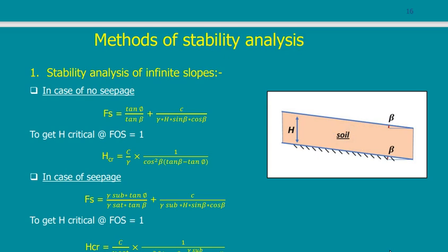Sometimes you might have seen videos of something called mud flow, where something like a mountain is moving down to the bottom. What is happening? You have a top soft soil, and this soft soil is very, very soft and does not have any shearing resistance, so it starts to slide on the stronger soils below. So it will start to move down here. In this case, we say that this is an infinite slope because it has no limit. It can take any area and fall down.